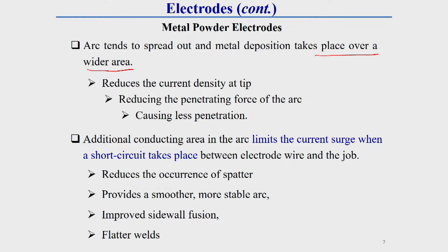Due to this extra conduction of current through the flux cover, it reduces the occurrence of spatter, provides a smoother and more stable arc, and improves side-wall fusion and flatter welds.